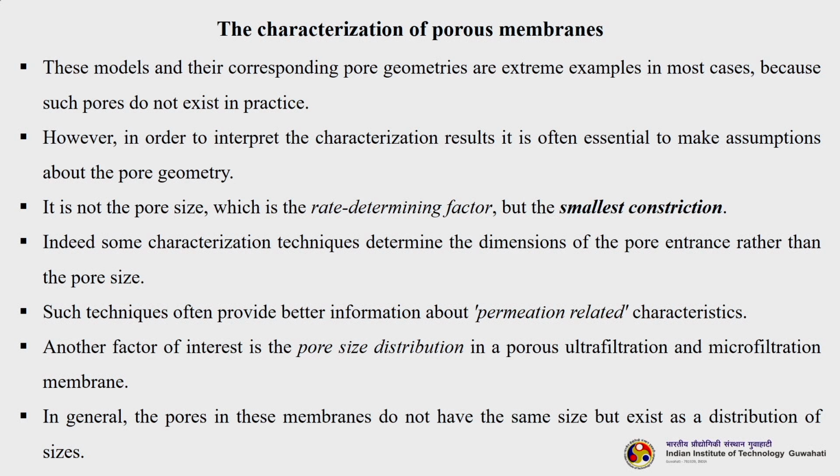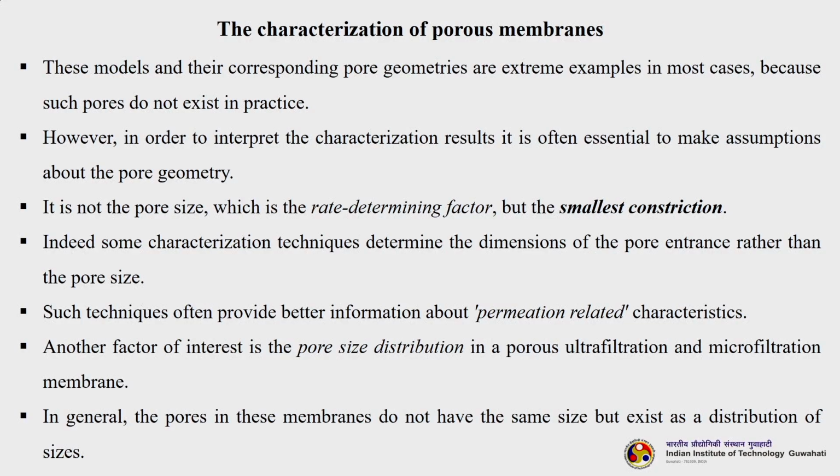The pore size we are characterizing is nothing but the diameter of the pore on the surface, but that is not the rate determining factor, nor what decides whether a particular solute will permeate through a particular pore. What decides is the smallest constriction inside the pore. Indeed, some characterization techniques determine the dimensions of the pore entrance rather than the pore size. Such techniques often provide better information about permeation related characteristics.